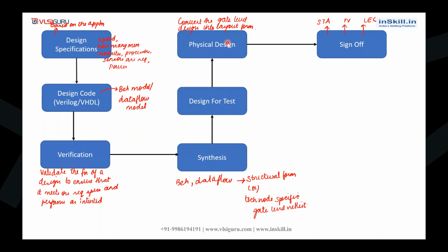That's why logical equivalence check is done to check whether the final design is logically equivalent to the original design or not. Actually, LEC will be done after every stage, that is after synthesis, after DFT, after PD, like that.